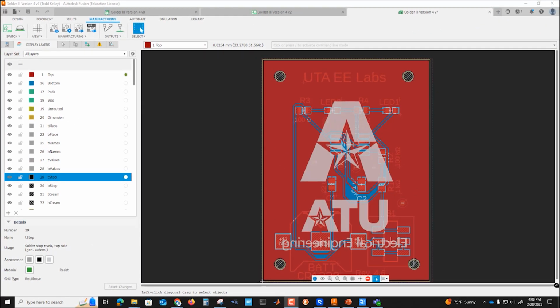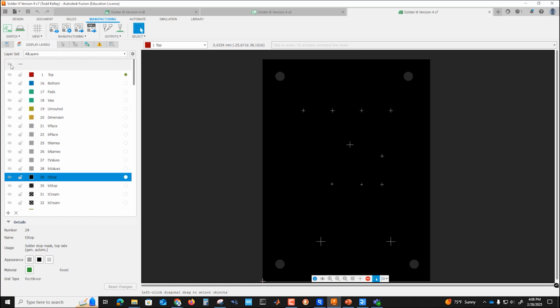This video covers how to order a stencil for your surface mount PCB. Here we have the Solder 3 Workshop SMD PCB open in Fusion in the PCB view. First, let's turn off all the layers. So under your display layers, turn it all off.